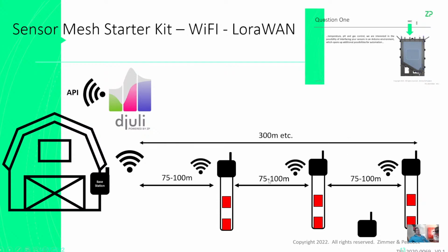The reason we do all of this is because you can get signal out of sensors, but on occasions, if the flow is chaotic, you can get a lot of noise in the data, and that needs to be smoothed out. If, for example, the plasma generator is going on and off, the baseline or the signal will move around quite a bit. So you have to understand these things, and you have to process the data accordingly.